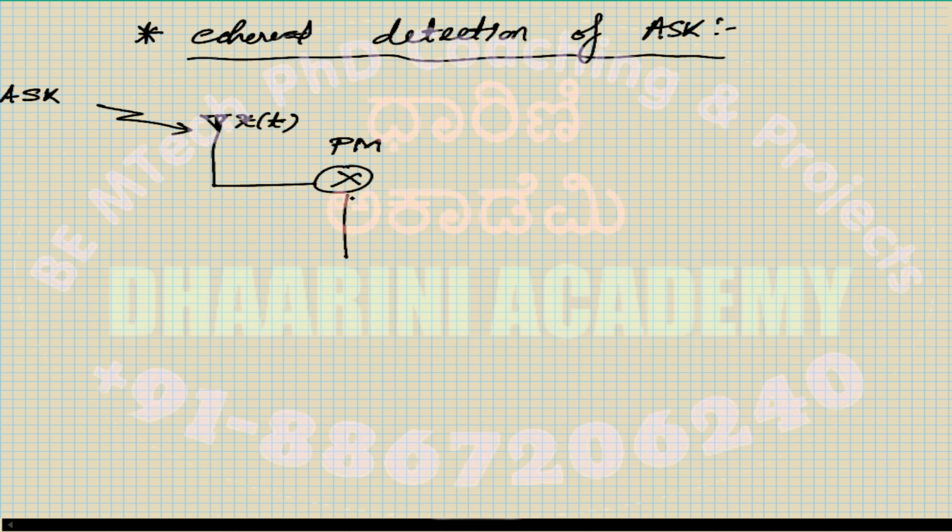Now it is a demodulator circuit, and since this demodulator or the receiver knows the frequency of the carrier, it directly generates that and keeps it ready. So phi 1 of t is available here as well, because it knows, right? So square root of 2 by Tb, the cos function is already generated, cos of 2 pi fc t, because fc is known to you, which means you can definitely generate this.